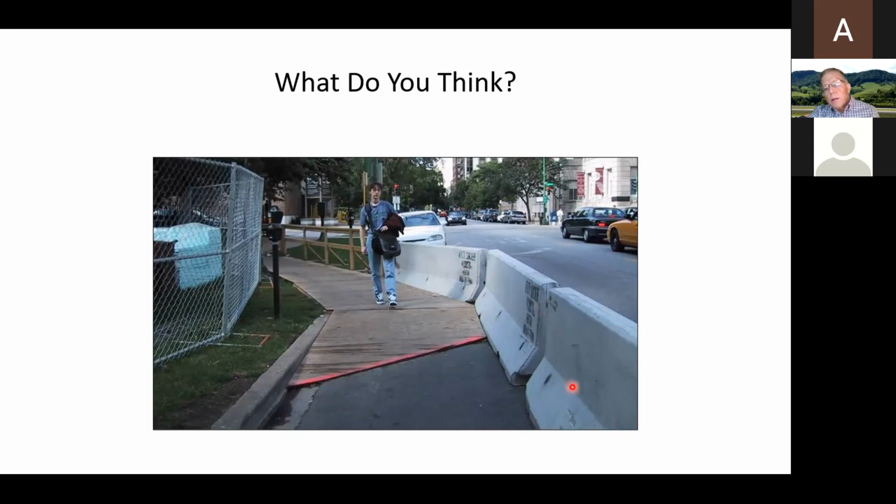And they're using temporary traffic barriers here. I commend them for that, but the MUTCD would say they need to be interlocked and continuous, and these don't appear to be interlocked and continuous. There's a curb ramp here, or a ramp. I'm not sure why they didn't sort of square that off. And my concern here is that looks like a pretty good lip there at that piece of plywood. So you might want to have some sort of a beveling or wedge there to make that an easier transition for a wheelchair.